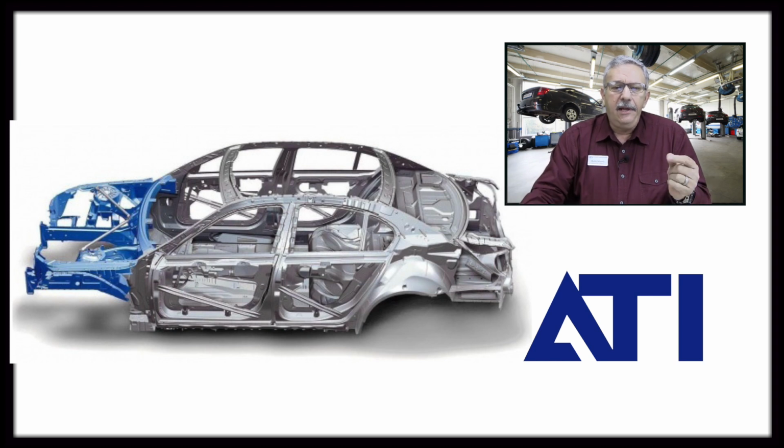This is really important because as we look at those bolt-on parts, the gap and flush, which we're going to talk about more in detail, are a visual indicator that you will use to identify how far the damage has traveled through the vehicle. Visual indicators are always probably our most important aspect of doing the inspection of the vehicles, because we don't measure initially. So the first thing we're going to do is ask, what are the things that I can see that will tell me that there's been movement in the vehicle?